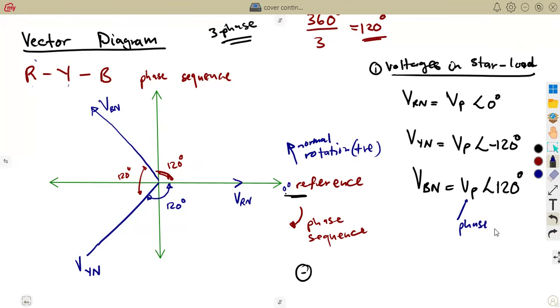This is simply our phase voltage from what? From VL, all right? VP is equal to VL over the square root of what? VL over the square root of 3 in star. Remember, you're dealing with a star load. It'll be different working with a delta. On a delta, we shall be working with something else. So this is what you're going to need for the voltages.